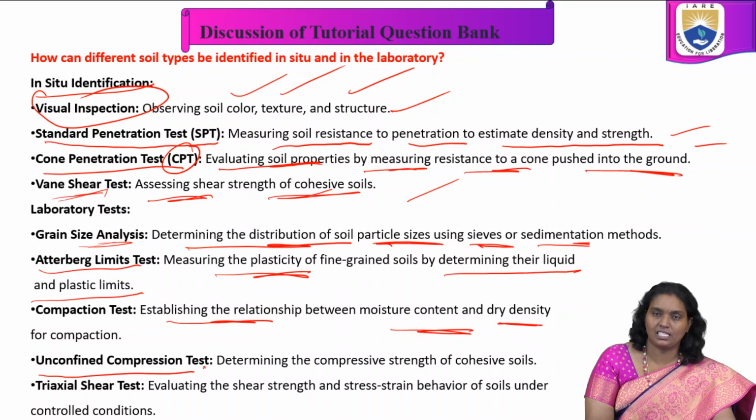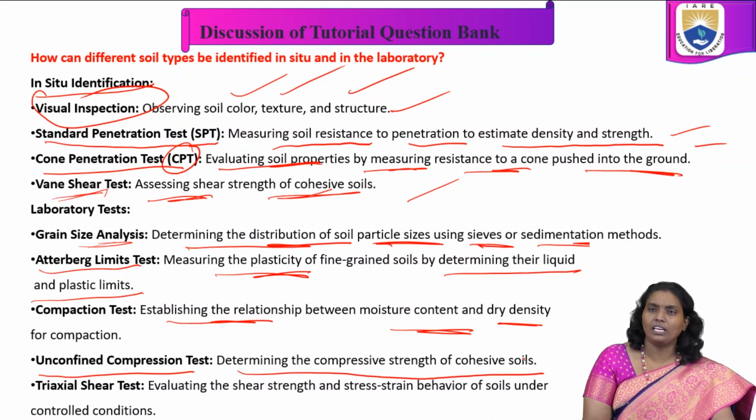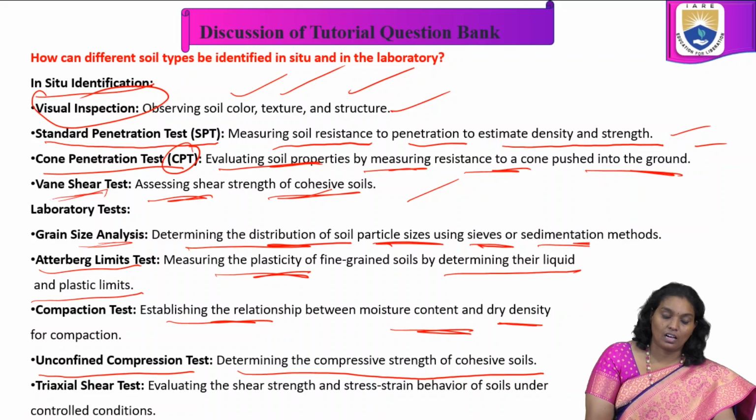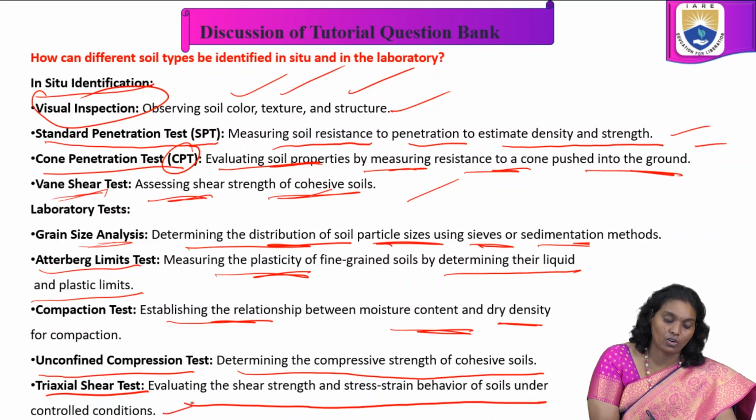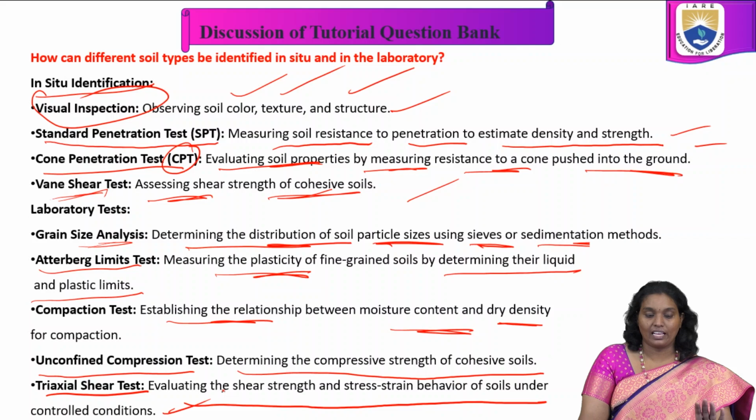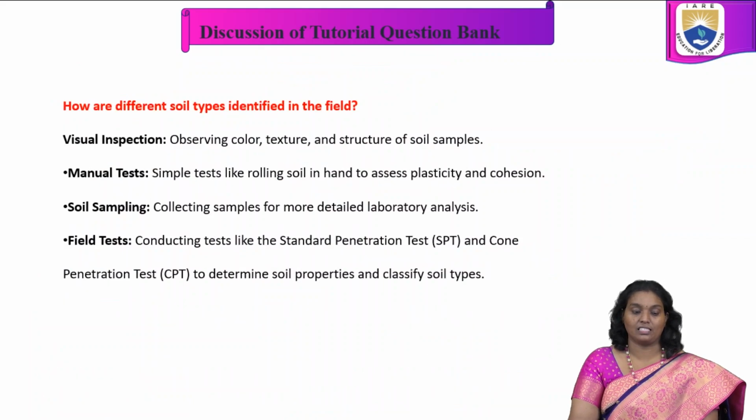Unconfined compression test, determining the compressive strength of cohesive soils. And also triaxial shear test, evaluating the shear strength and stress-strain behavior of soils under controlled conditions.